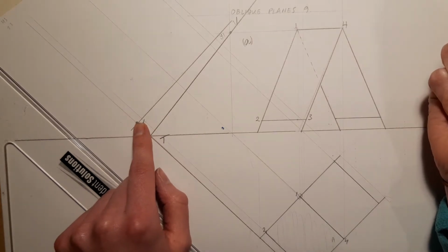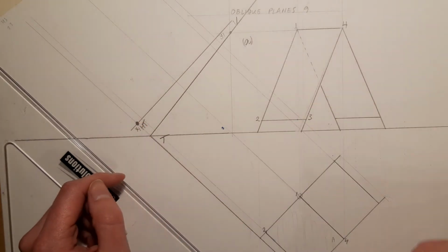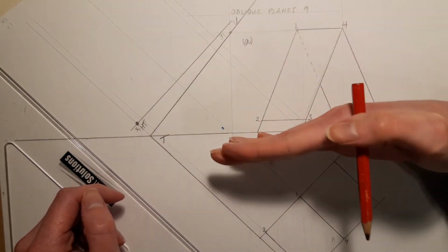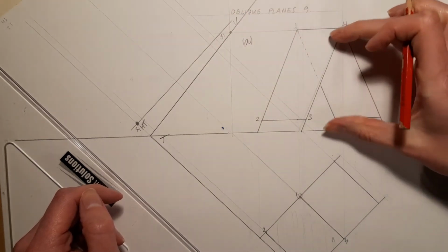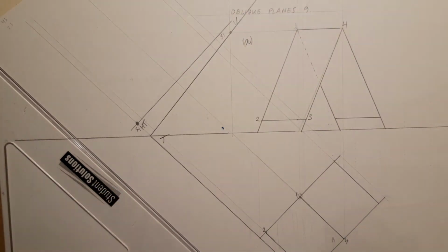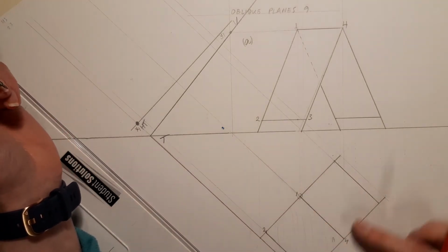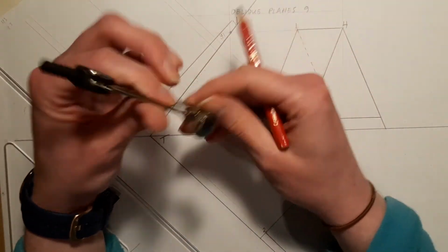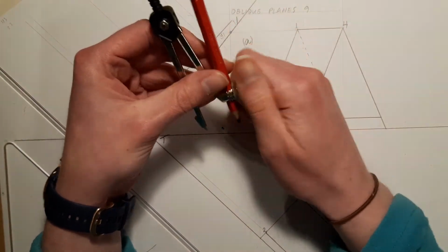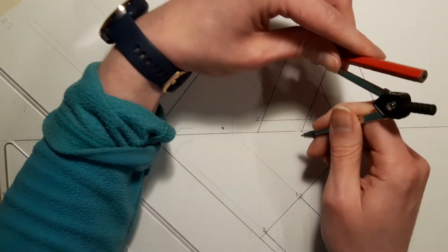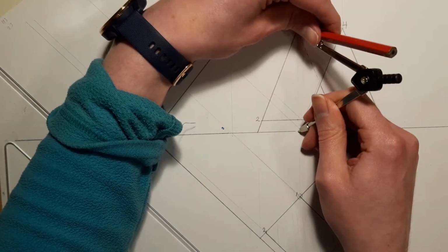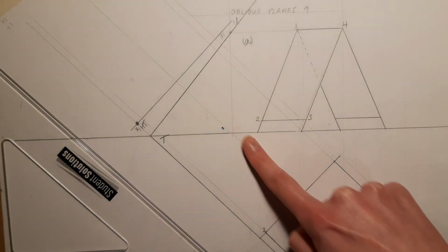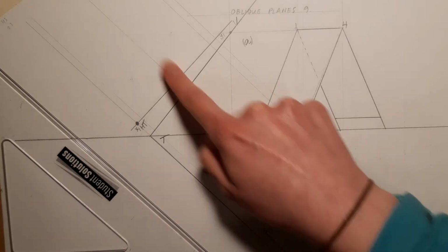And in an auxiliary, you always work from your last XY line back. So when I moved out here, if I work backwards, it goes into plan and then it goes back into elevation. So this is my last XY line back. So I'm taking heights. What I need to do here is to get the height of 1 and 4, we just take the height from the elevation and transfer it into our new auxiliary. So 1 and 4 are the exact same height. It doesn't matter if you take the height at 1 or at 4, because when we look in there, 1 and 4 are going to be in line with each other, as you can see.